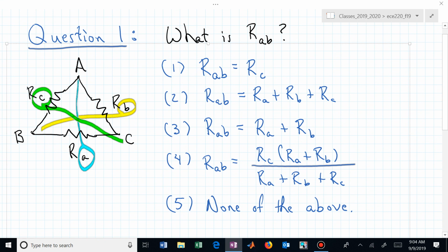If you look at the vertex for A and look directly across from it, right below it, that's where R sub A is going to be located, R sub lower A. Our delta connection will have alphabetical subscripts, R sub A, R sub B, and R sub C. And they are located opposite their vertex.